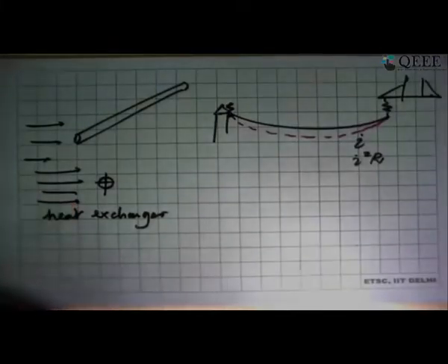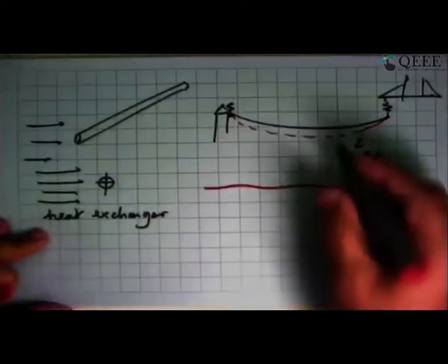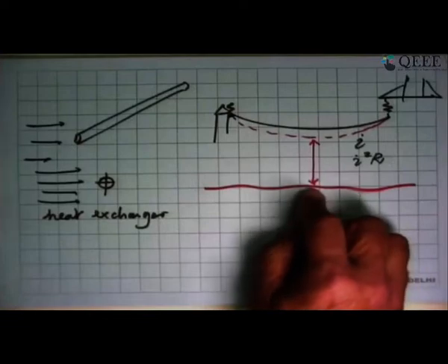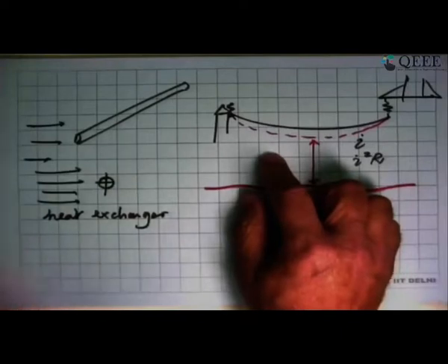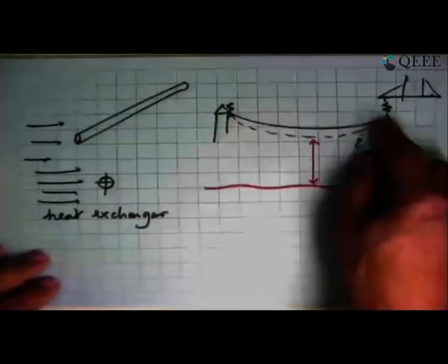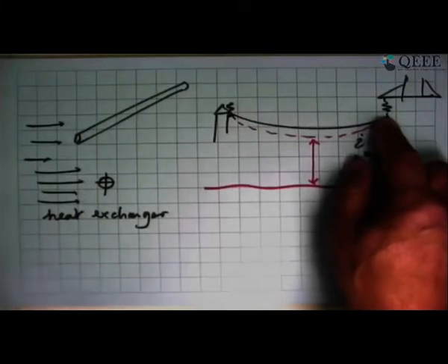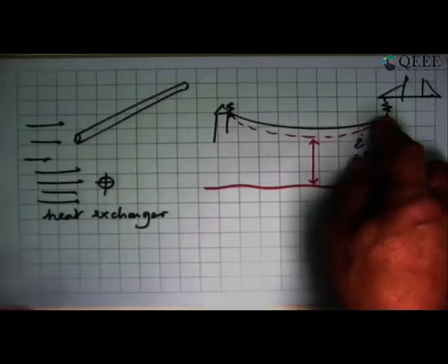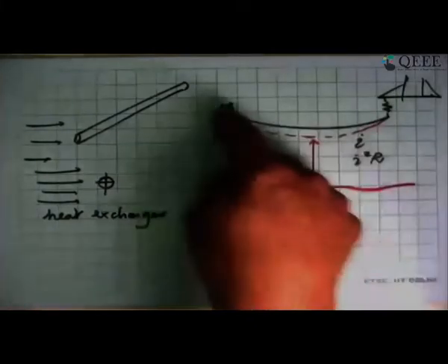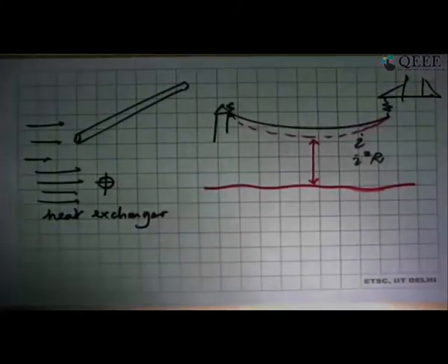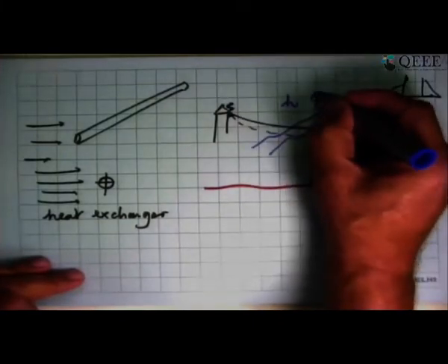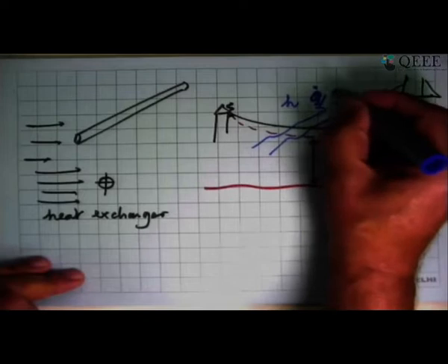The result is that the distance between the cable and the ground decreases. So the leakage current from the cable to the earth will start going up, and now we have a problem. On top of that, if there is a lot of pollution, it will make a bad problem even worse. That could lead to tripping of the power line, because you get an unstable electrical situation and you want to protect all your equipment, and this could lead to a complete grid collapse. This has happened in some cases. To estimate the cooling of this wire, you have a wire which is hanging with airflow taking heat away. How can I estimate the average heat transfer coefficient, and then finally the Q dot per unit length of the wire?